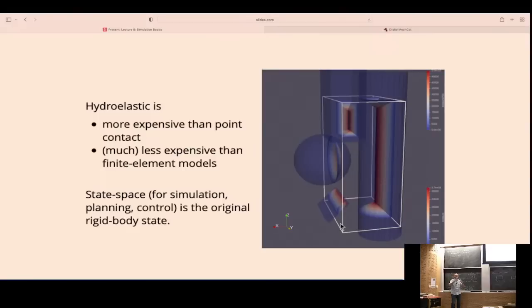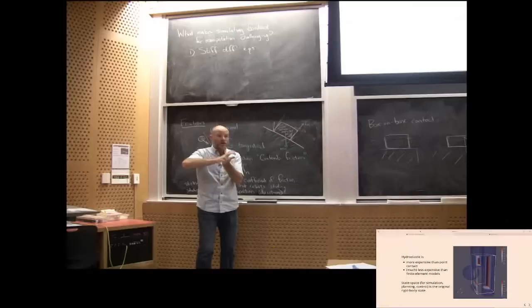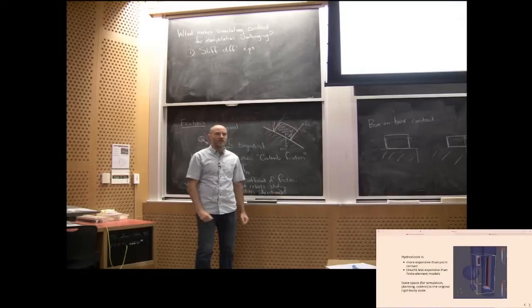We're allowing penetration. So the contact geometry doesn't change, but at every instant we're allowing the penetration and computing an integral over the penetration to produce the force. So this is good for soft simulation in the low deformation mode. If you can say my geometry is roughly not changing, but I want it to be squishy a little bit, this is a good model for that, right? Or for nearly rigid, if I turn K up on my stiffness, I can simulate pretty nearly rigid things with this, okay? It's not going to simulate a plush toy. If you want to pick up a plush toy and shake it around, or a rope or cloth, this is not the right model for that.